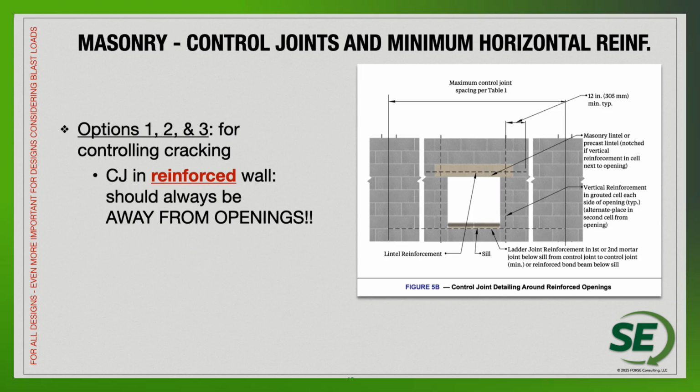So making sure that those doors and openings don't succumb to the pressures that you'd have with the blast loading. But say that we do have those elements. What do we want for the masonry wall around those openings? We certainly want to have a reinforced lintel that's able to pick up some of the loads, and more heavily reinforced jamb elements. We really want that area around the openings to be extremely robust and able to handle the higher impact forces and stresses that you can have due to some of those openings that could be within that blast resistant wall.